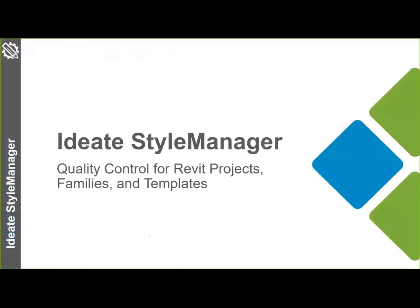And lastly, but not least, is our third tool that helps you ensure Revit model health, and that's called Ideate Style Manager. Style Manager was just introduced last summer, and it allows you quality control for Revit projects and your families and templates. Where you saw with Ideate Explorer, I was able to audit elements that have already been placed and fix them, like all the line styles, right? And fix where things were located. Style Manager is really allowing you to fix it before it becomes a problem, being able to understand where these elements are being used in a project, and then being able to modify them or delete them or reduce them to the styles that you want.